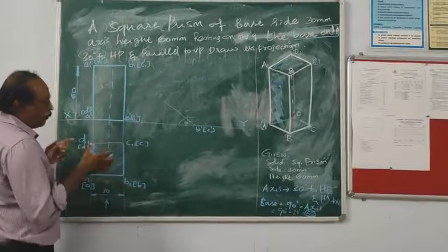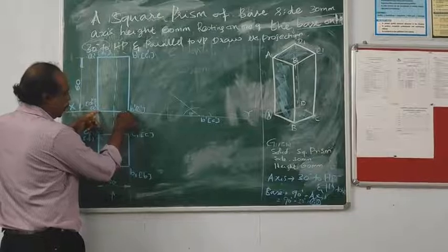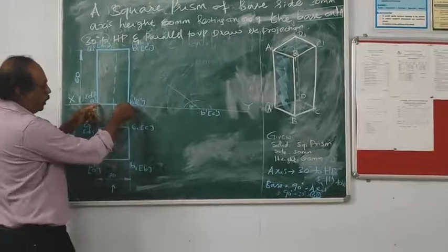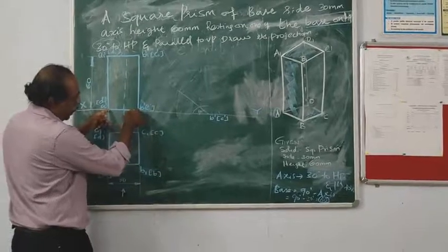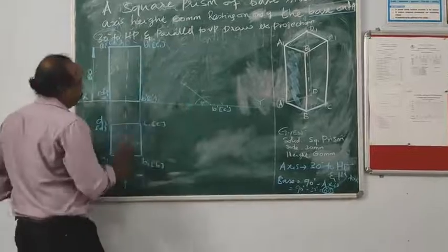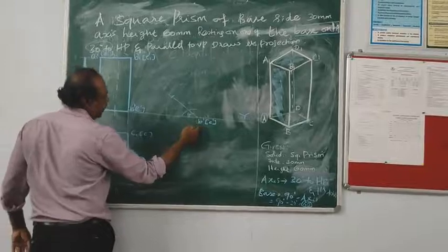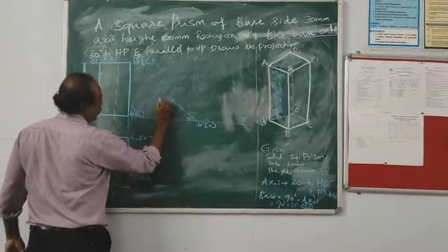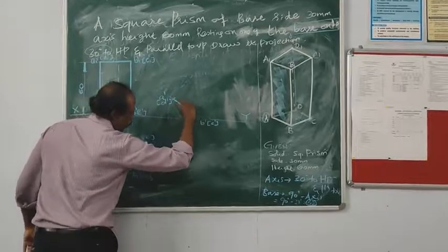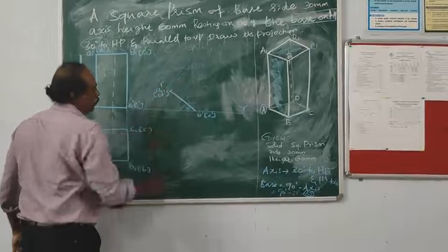Then use the compass. Pin point is here and pencil point is here to measure the dimension. Then keep the compass and come here and make the arc like this. So the same information is printed here. This is b dash, c dash, here a dash, b dash. Then we have to draw the line using an HB pencil. There is the unwanted portion.